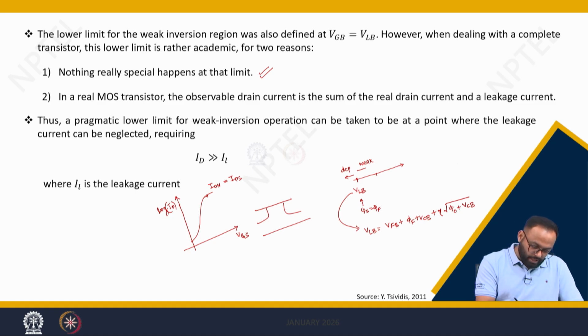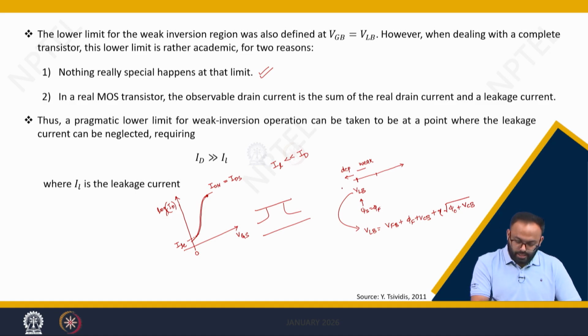But to some extent it will go below, and when this current is near about 0 voltage, then we call it leakage current. So we can simply consider that leakage current is negligible as compared to the main current which is flowing between source and drain, so the arrow will be on this side, in the sense the current will be IDS, drain to source.